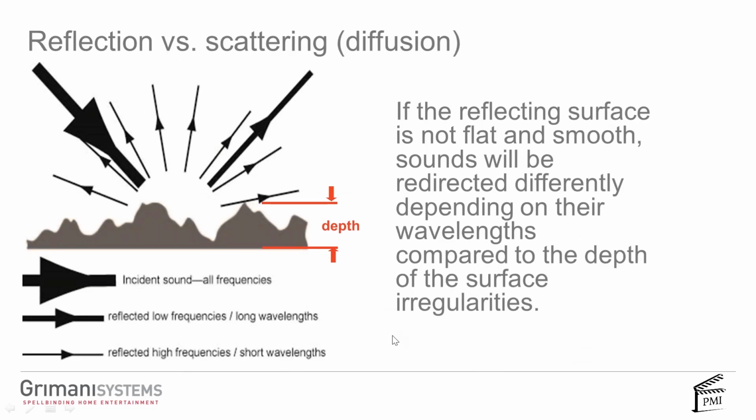All right. So the idea of a diffuser is it's a surface that's uneven, where the incident sound hits a surface with different shapes and different depths. And you can actually calculate these curves and shapes very scientifically so that the re-reflection is completely smooth. You want a good diffuser to have a return into the room that scatters the energy very evenly, just like a Lambertian screen for video.